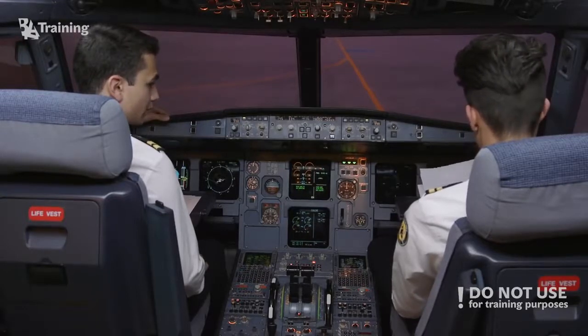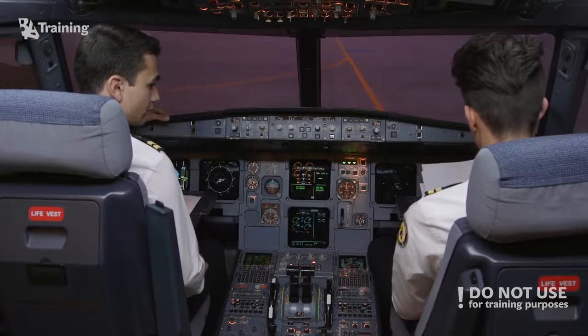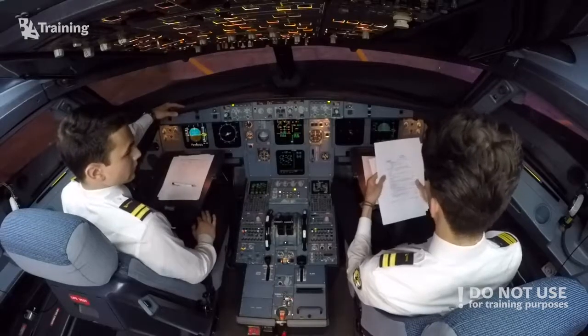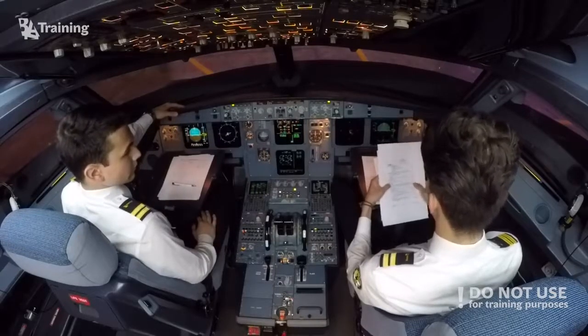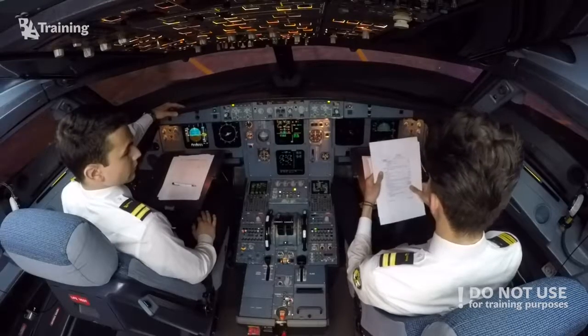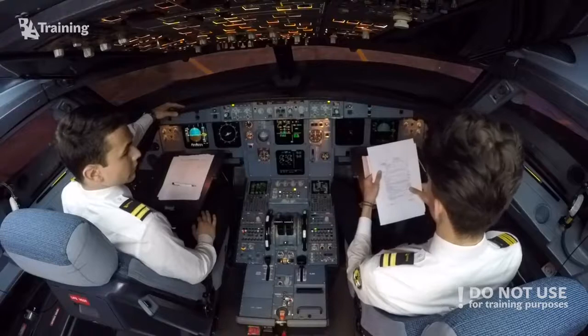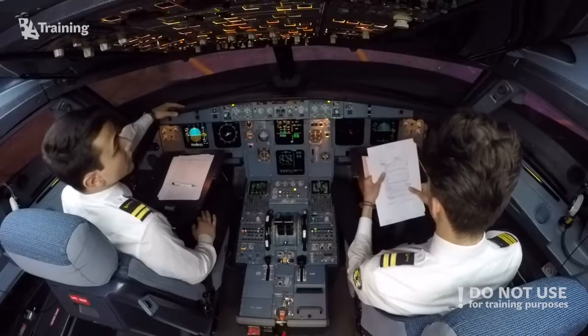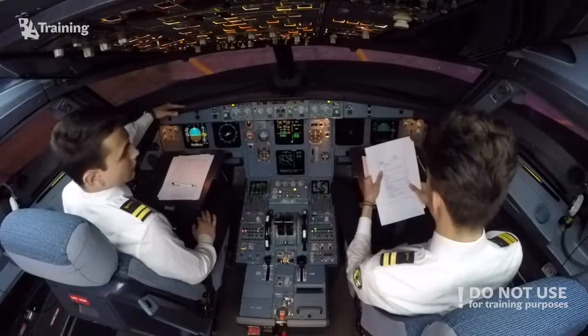Engine master on, chronometer start, igniters A and B check on, fuel flow increase check, the 15 seconds maximum after fuel flow increase, EGT increase check, and N1 increase check. If the electrical power supply is interrupted during the start sequence, indicated by loss of ECAM displays, abort the start by setting the engine master lever to off, then perform a 30-second dry run.